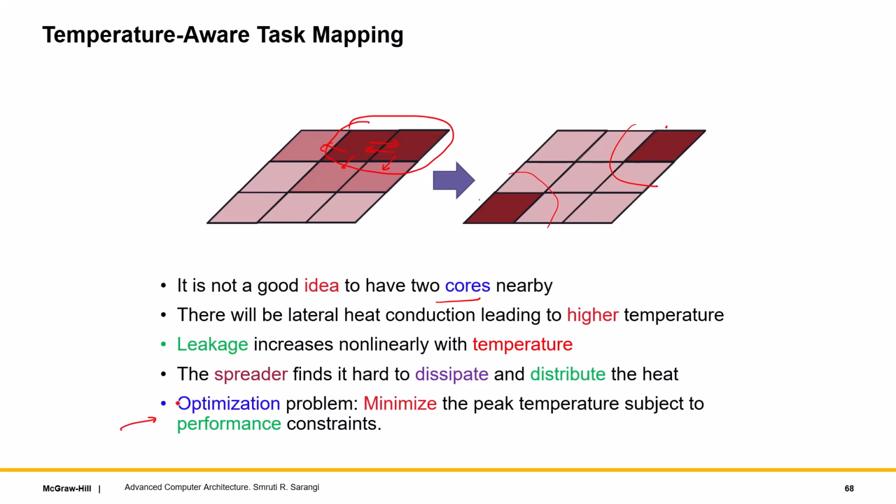Typically, we have a constraint on the peak temperature. Or we define something as the TDP, thermal design power, which is the maximum amount of power that the chip can dissipate before reaching a temperature cutoff. So the idea is that even when the total power is much lower than the TDP, hotspots can still form, which is why the hardware will be forced to bring in DVFS. But again, with proper scheduling of the jobs, a lot of this can be managed.